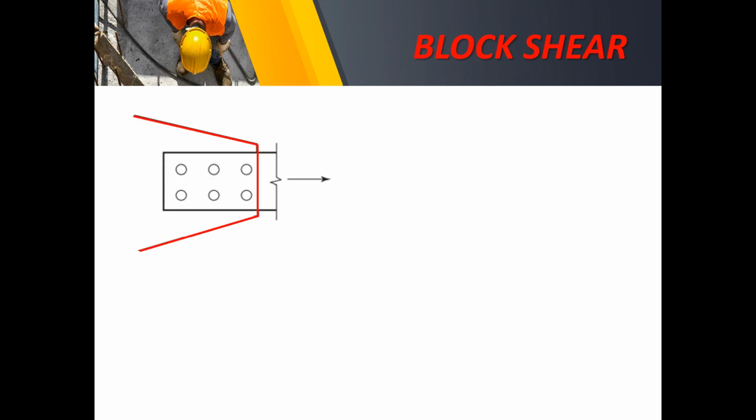When we have the gusset plate, all we have to remember is to determine the edge of that gusset plate along the direction of our force, so that we just have to project that edge up to the half of the bolt at the far end.